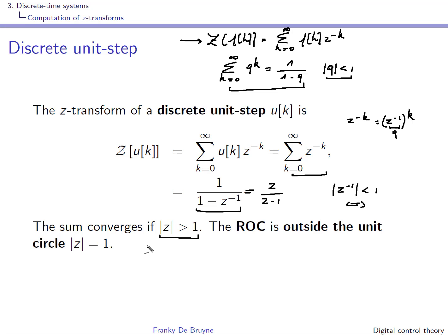Okay, so another way to obtain the region of convergence is to have a look at the pole, and the pole is located, this will be the unit circle, so the pole is located over here. Okay, so we know that what you have to do is take the pole with the maximum radius. Clearly, since there is one pole, it's the pole in 1, and then you draw a circle on that, and it will be the outside of this circle, and this is the region of convergence, and this is also what we had obtained using this condition over here.